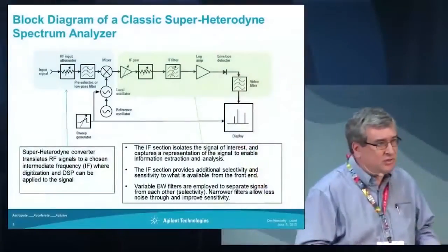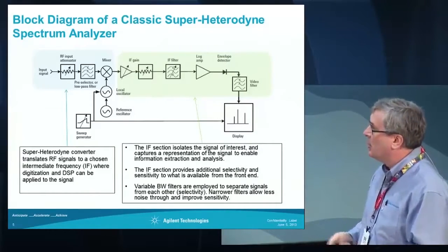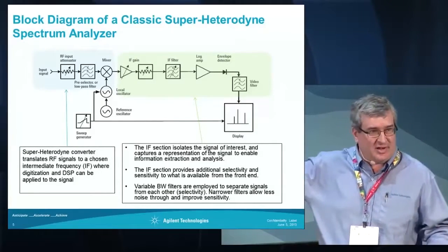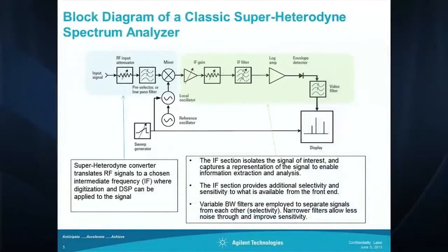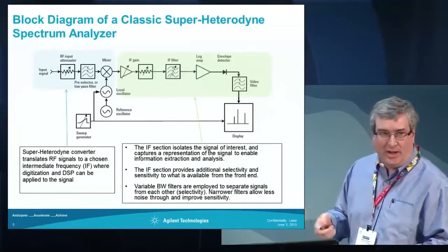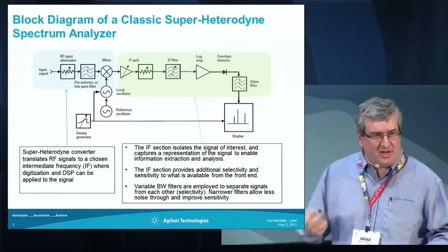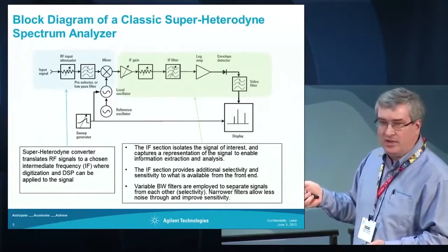So this is the block diagram of a classic swept superheterodyne spectrum analyzer, going all the way back. You'll open up AppNote 150, you'll find this exact diagram. You'll open anybody's introductory slides on a spectrum analyzer, you see the same thing. We're coming in with our RF signal here. We do some signal conditioning to get our amplitudes right, so there'll be attenuators and preamps sitting here. We do some filtering to make sure that we don't alias over our mixer.